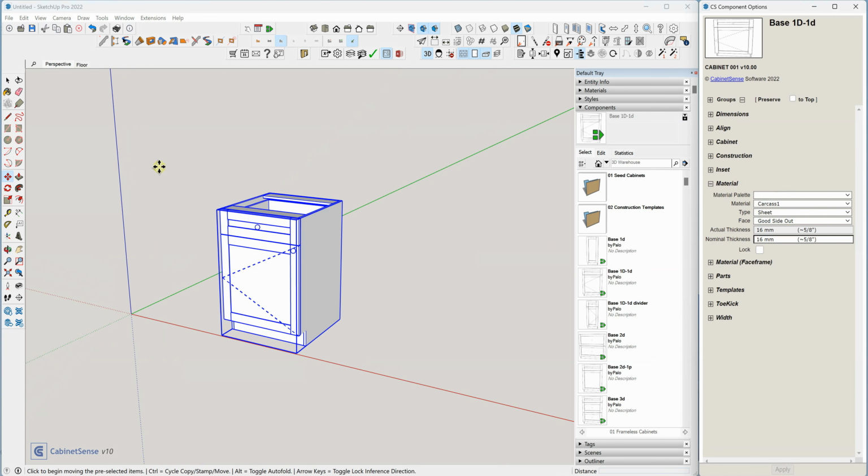And it's showing up as blank, but if you click on the drop-down list, it's actually showing 3 question marks and the word default. The 3 question marks tell you that it is looking for a palette called default, but it can't find it. So it's basically undefined.